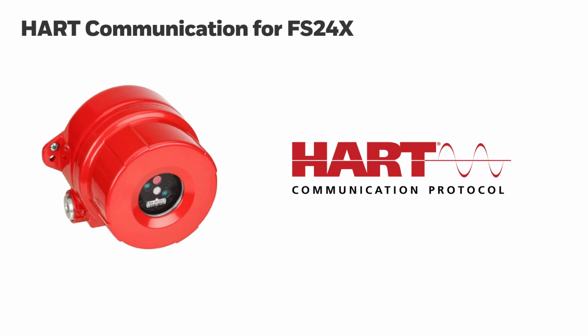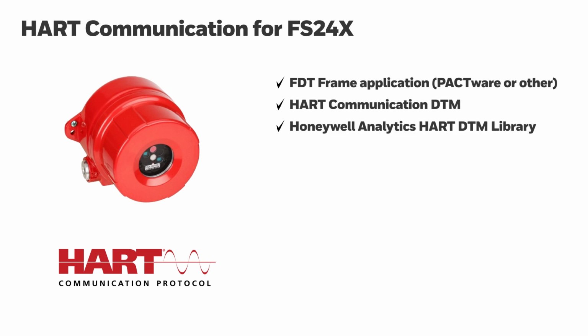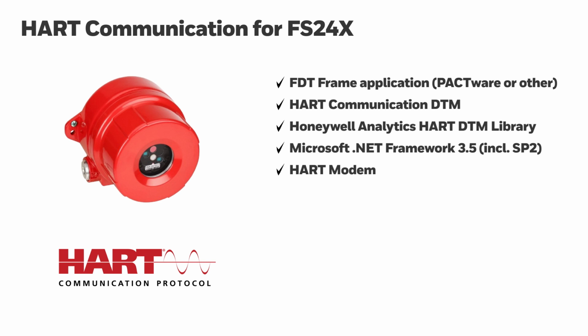And the FS24X should have one optional HART module installed to use HART communication. In order to be able to use the FS24X HART DTM and to go online with the device, you need the following components: FDT frame application, PACTware or some other FDT application supporting FDT 1.2.x, HART communication DTM, Honeywell Analytics HART DTM library, Microsoft .NET Framework 3.5, and a HART modem.